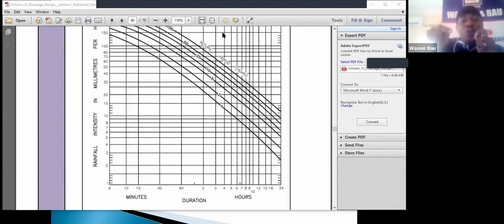Because by the time you now do your unit hydrograph with that intense intensity, it will be giving you discharge. When you multiply by the area, if you multiply 100 mm by, say, 1,000 hectares, and the volume is going to come to one particular channel, then you know that that channel is going to flood. So that's the secret. All this I'm saying is trying to explain to you the meaning of time of concentration, because it's important that you know time of concentration or time of flow.